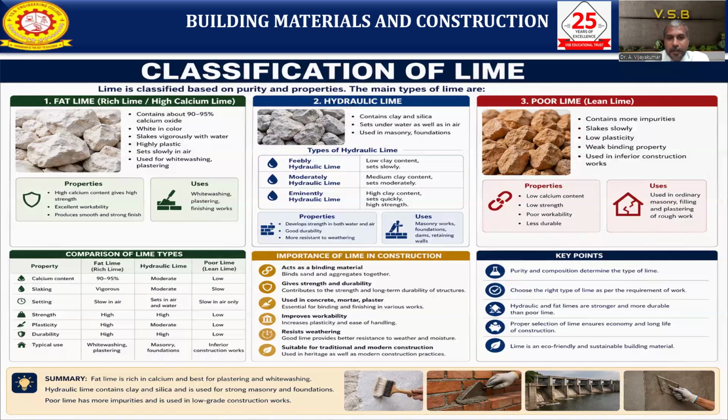The property of hydraulic lime is that it develops strength both in air as well as in water. It has good durability and is more resistant to weathering. This hydraulic lime is used in masonry work, foundations, dams, and retaining walls, wherever hydraulic conditions are present.